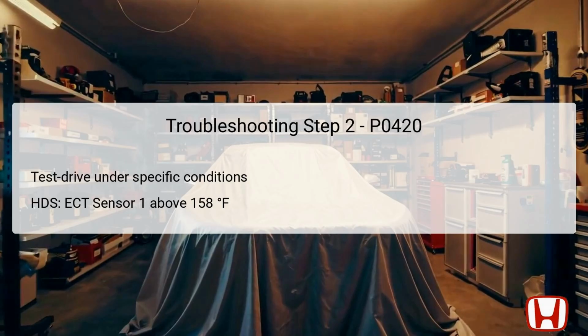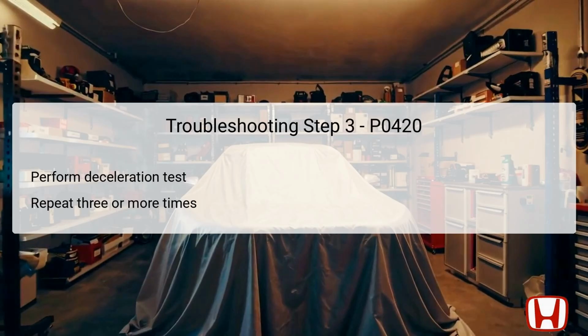Following these guidelines is essential for gathering accurate diagnostic information to determine if there is a persistent issue with the catalytic system. The third troubleshooting step involves performing a deceleration test to monitor the vehicle's exhaust performance and sensor outputs. The driver should maintain the vehicle's speed at 55 to 75 miles per hour, 90 to 120 kilometers per hour, for a minimum of 10 seconds, and then carry out a full throttle closure for deceleration.